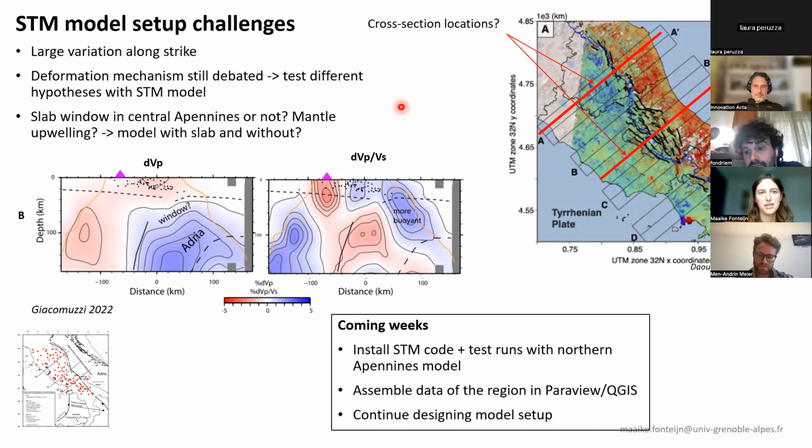Okay, thank you. And what is the definition of stationarity according to you? Well, of course, when we are dealing with the seismic process, stationary is something that occurs, let's say, randomly, and in which the mean occurrence time of something has the same variation. The variation is equal to the mean. So stationarity does not mean that you have a fixed recurrence time for earthquakes, but earthquakes that occur randomly, but with a given range of variation that is represented by the mean occurrence time.